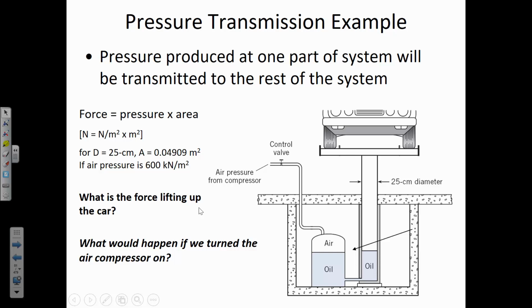I mean, you know instinctually what's going to happen if you turn on the air compressor, right? Is nothing going to happen? The car goes lower or the car goes higher? It goes higher. How come? Why does the car go up? All right, good. So you turn on the air compressor, you've got more pressure in here, so more pressure in the oil, more pressure up.